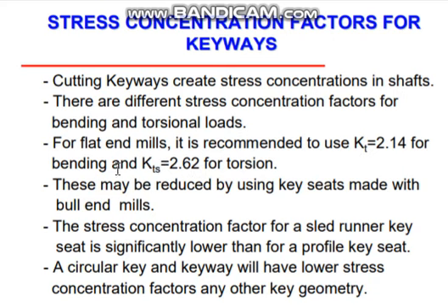So here also, if you have cut it with flat end milling cutters, then you have to use KT 2.14 for bending. So then this is not a T, it should be M. KM will be 2.14 and KT is 2.62 for torsion.